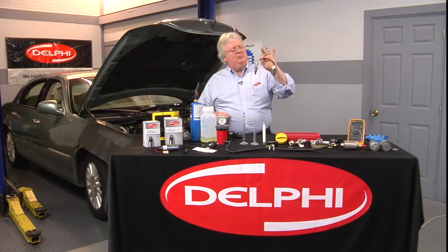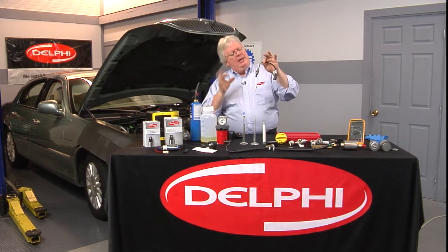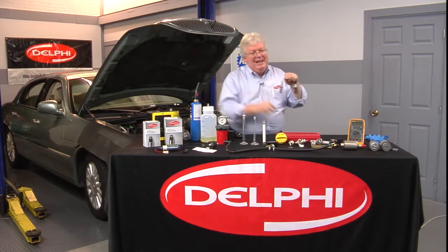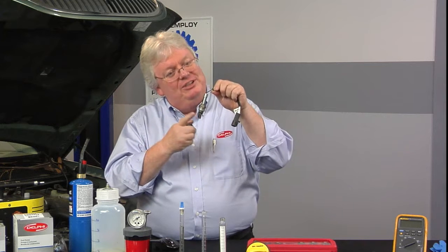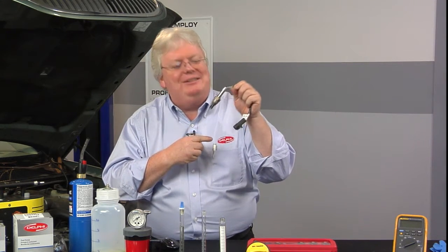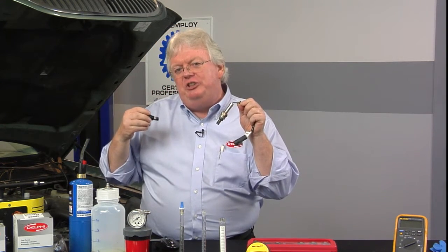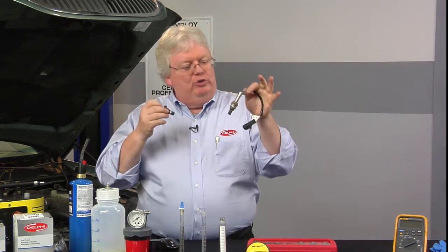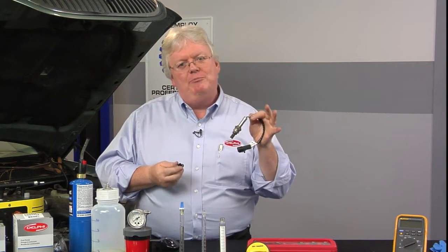Normally a lot of techs will say, well, if it's misfiring, let's say it's an ignition misfire, very popular, very common, it doesn't make combustion because there's no spark. The fuel injector, on the other hand, still sprays. Wouldn't it make the mixture rich? Yes, but what does this measure? O2 only. It doesn't measure hydrocarbons. It's not a 5-gas analyzer, it's a 1-gas analyzer, O2. So the oxygen that didn't burn, when the fuel sprayed but the spark didn't ignite it, goes right into the exhaust and makes the sensor think it's lean. So fuel trim numbers go up.